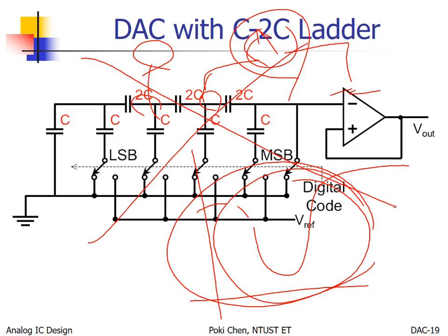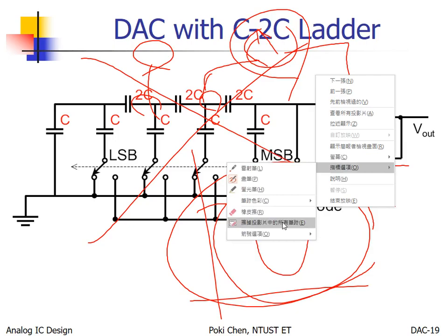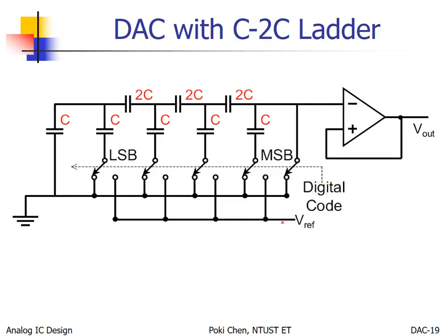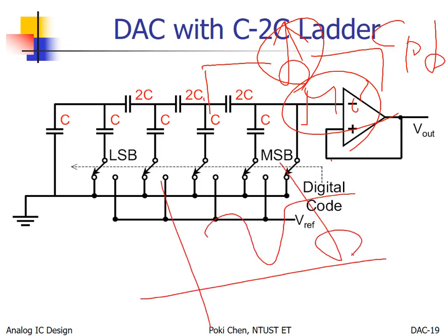And we say, hey, all right, I know it. So how to solve the problem? Again, for the switches, I mean MOS switches, you can reduce their size very much. You can make them as small as possible. Then the parasitic capacitance can be reduced. The nonlinearity can be reduced, right? Bingo, you make it.